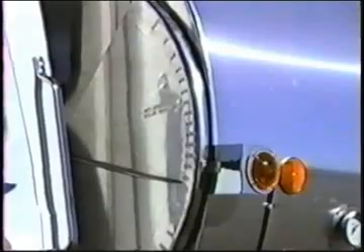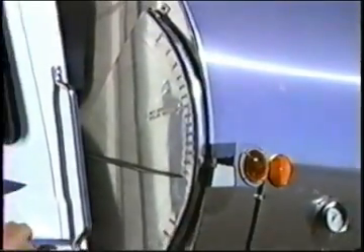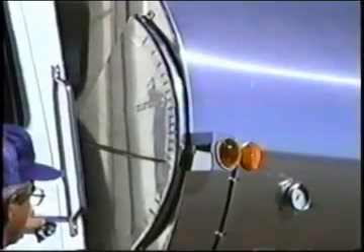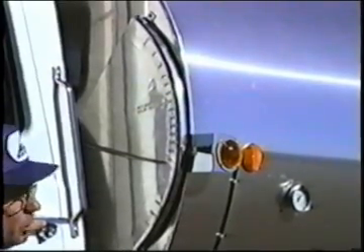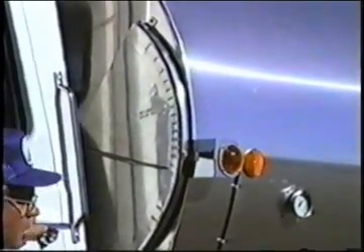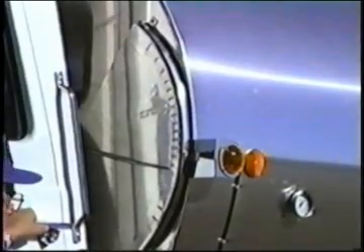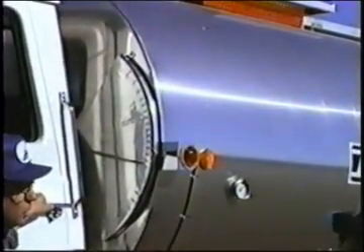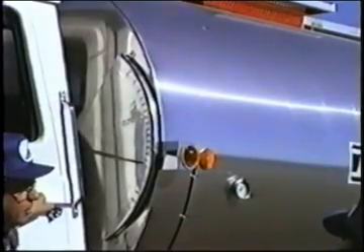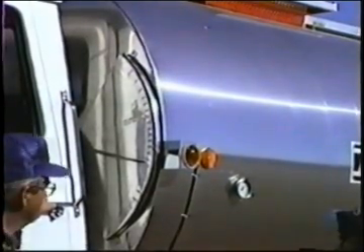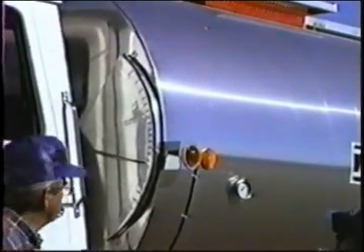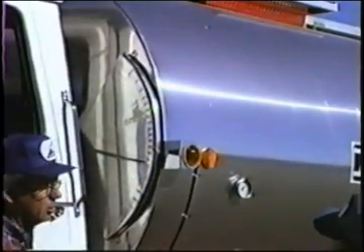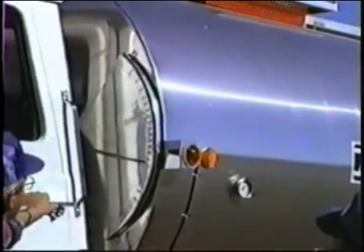The float gauge, of course, is affected by the up and down grade as well as the side grade of the truck. Anytime you're comparing numbers from the float gauge, like if you want to see how much material you shoot out of the tank, be certain that the truck is in exactly the same position as it was when you read the gauge the first time. If we tip this truck down a couple of degrees, the float gauge may change as much as 25 or 30 gallons, so always be in the same position.